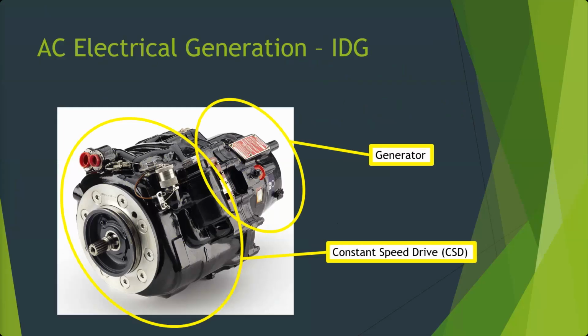The accessory gears are driving an input shaft to the constant speed drive. And then there's another piece going through that connects the constant speed drive to the generator, okay? Normally, you're going to see this configuration on the board, which is piggybacked. Okay, that's a lot more common. Again, I think this was weight and balance, size, making it fit within the cowling, that kind of thing.